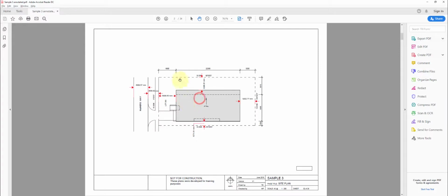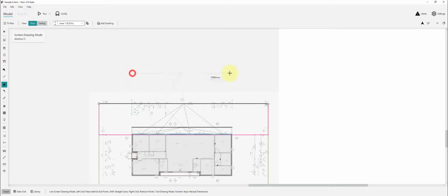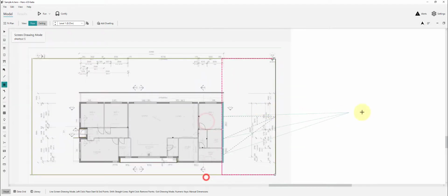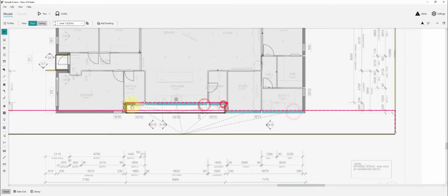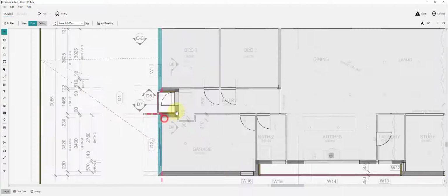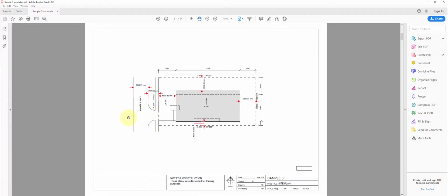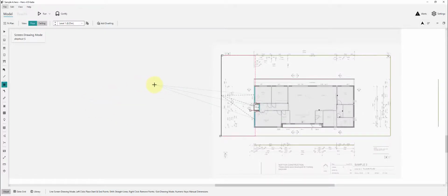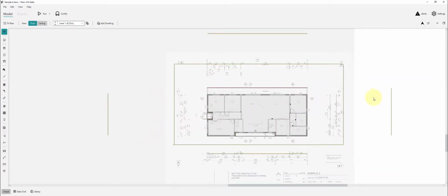We also have to put in kind of a reflected building onto the north, east and south. So again, we'll just quickly select those walls. It's going to be the same distance away from the fence as our dwelling is, and we'll just model it as a single screen, capturing the ridge height closest to us on a similar floor plan. This one's quite a way away. We've got a footpath and then a road, and then you'd assume another footpath and then another fence. So it's going to be some fair way up across here. Likely not to have much impact on the model at all. Alright, so that's our screens drawn in.